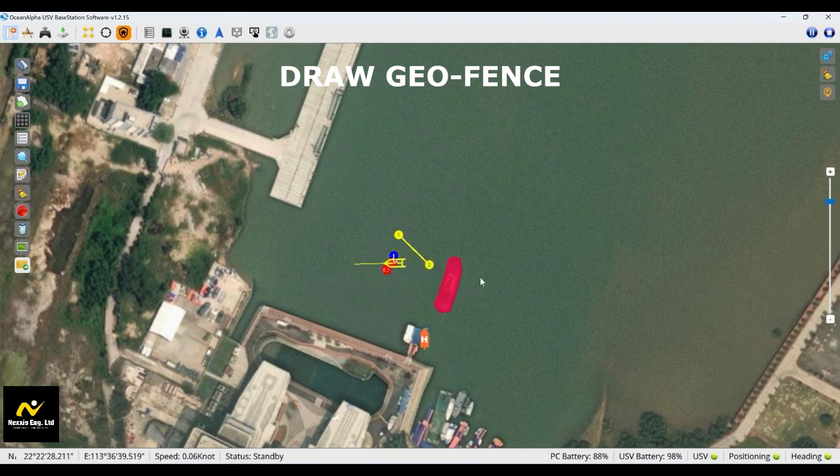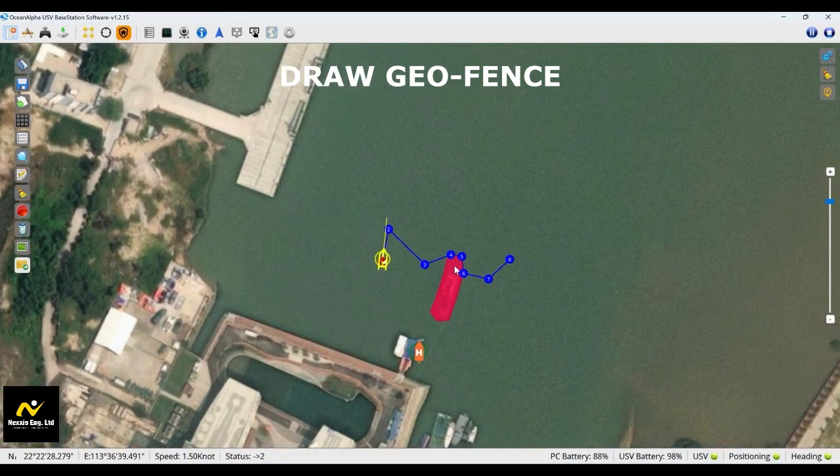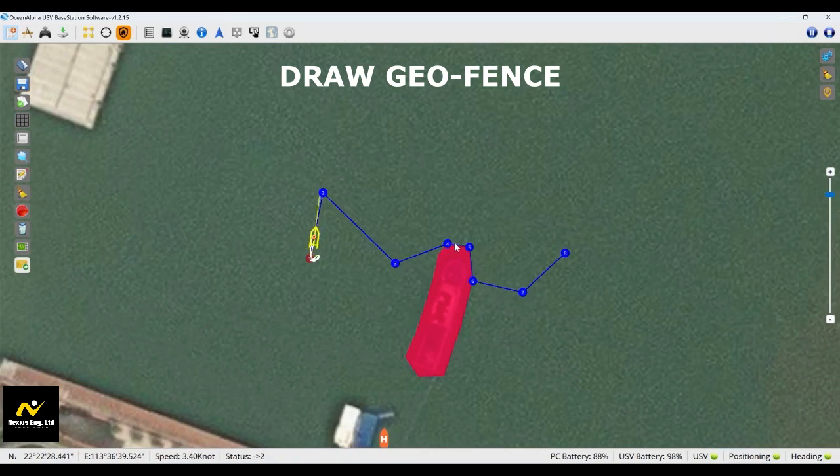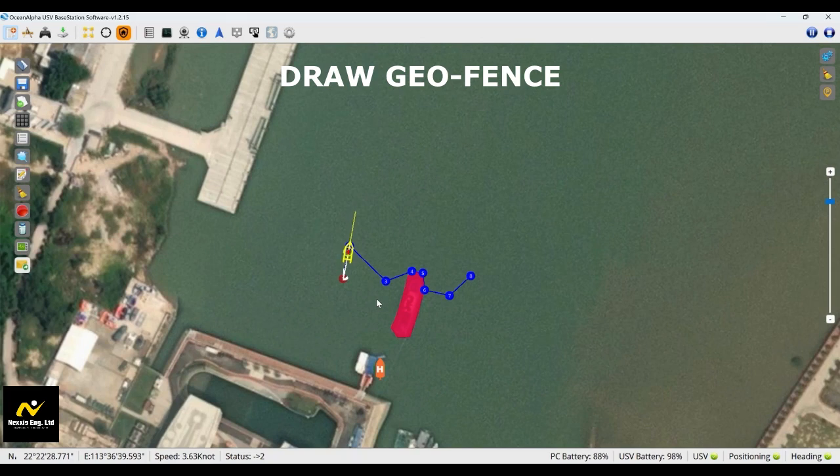From the video, you see it is highlighted red, so that when you plot your mission in the autonomous mode, it will go completely around it because it has been geofenced. This is very critical in mapping areas that are marshy or that have tree stumps or so many obstacles in such water bodies, tailings, or areas of interest.